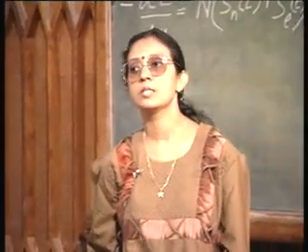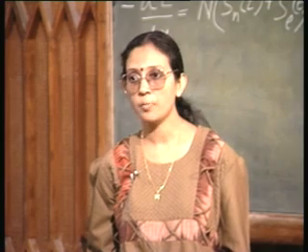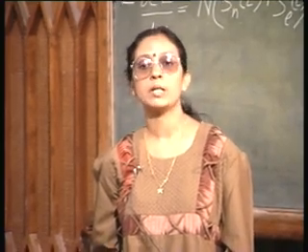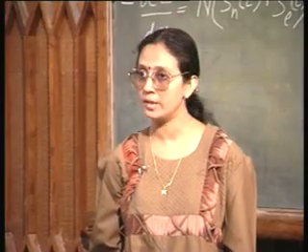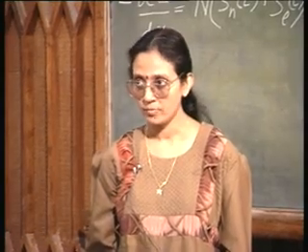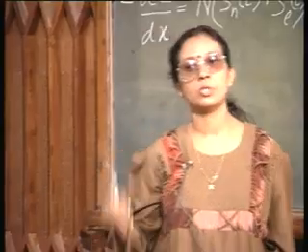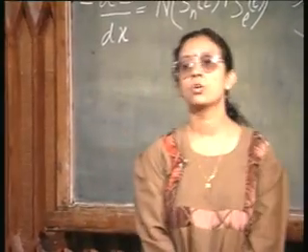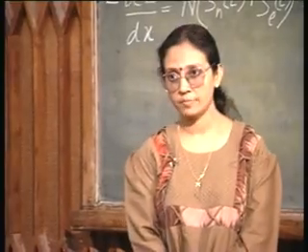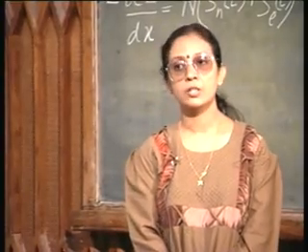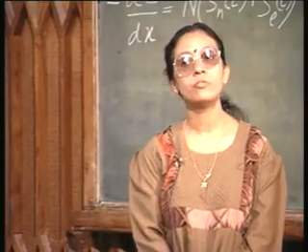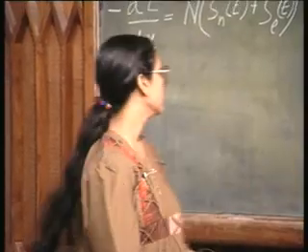When the ion energy becomes 0, that is the point where it comes to rest. Therefore, that is the point up to which the dopants have penetrated the semiconductor. So, just as in case of diffusion, I need to know how far the dopant has gone inside the semiconductor. And in ion implantation jargon, this is called the range of ions, the range, that is R.